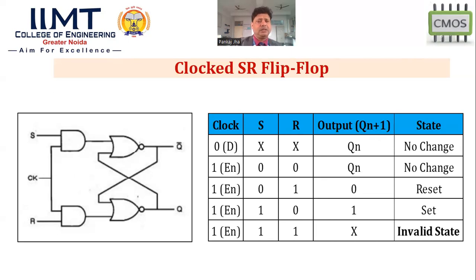So this is a gate level implementation or design of the SR flip-flop. Here, the latch is there. We have already discussed this NOR based latch. Now we are adding these two AND gates with the combination of the clock. This clock basically enables or synchronizes the output. That is, when we will get the next output is going to be decided by this clock. That's why some authors and some books write this as an enable condition.